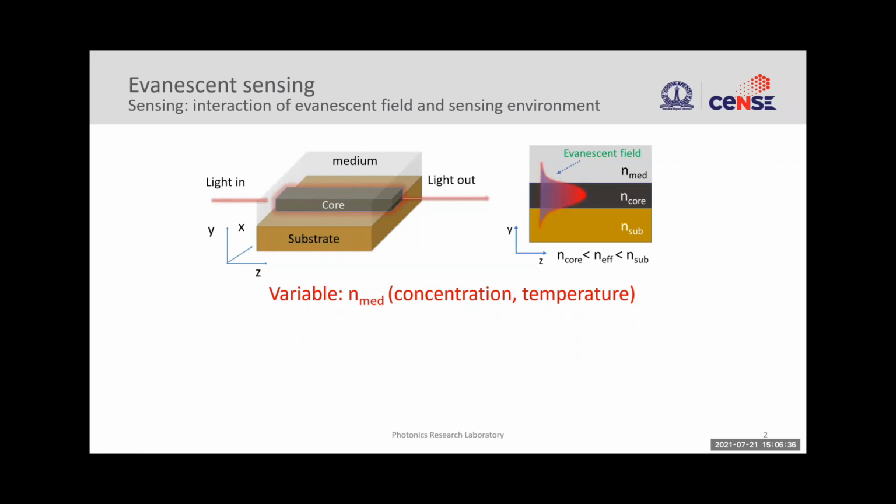So here we are primarily going to exploit a guided wave system for sensing. When I say guided wave system, we use waveguides. A waveguide has a core where all the light is confined, and the light that is confined will have its evanescent field extending beyond the core. The extended tail part is what we call the evanescent field. This field is going to interact with the environment, and this evanescent field interaction is what we are going to exploit.